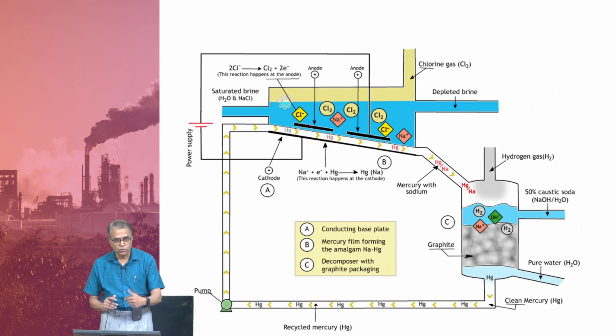The second aspect is the same thing, switching to the other electrode. This electrode is dipping inside an aqueous solution and getting chlorine, and wet chlorine is highly corrosive. If the chlorine is dry, at least for metals it is not as corrosive. For human beings, because of the mucous membrane, everything has got water, that is how wet chlorine is too bad. So, this is wet chlorine. So, one had to find out what is the metal that will conduct, but will still not be corroded away in the process of conducting electrons.